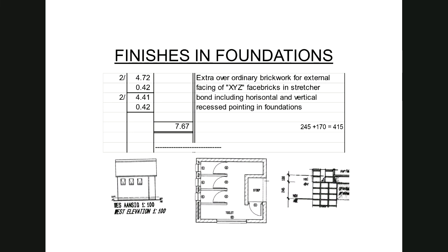Right, and then the last item that we have in the foundations is actually the finish. So I want you to look at the elevations on the drawing. I have merely cut and pasted one of the little elevations. I see my illustrations are slightly cut off, but I'm sure you can follow. So here you can see we have a face brick plinth up to our cut-off level.